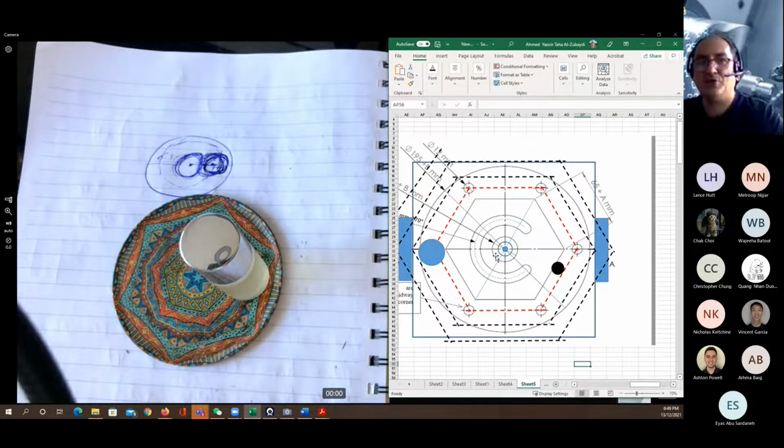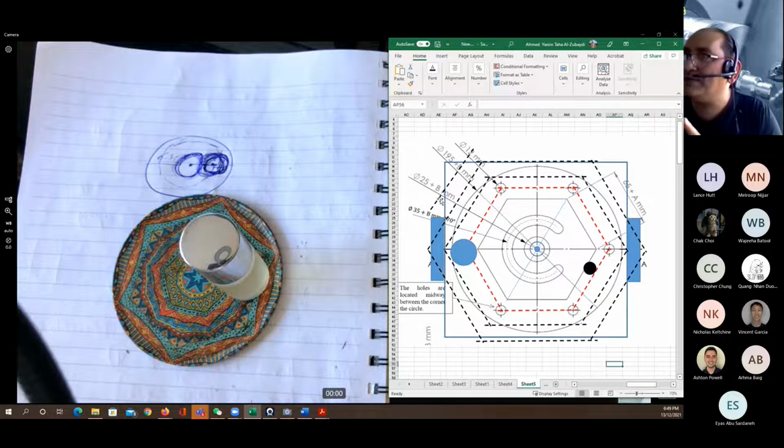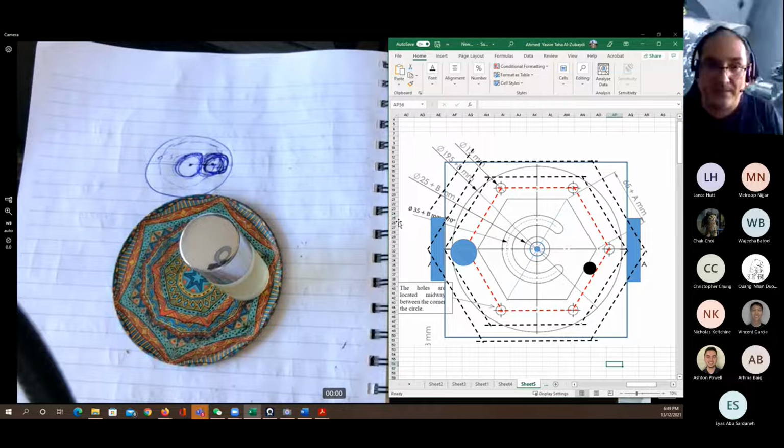Okay, so you subtract when you do the circle interference, circle cut from inside, you subtract. You always subtract. If you're going to confuse with that, use the radius. Don't use the diameter. Use the radius. So the radius of the inner circle, if its diameter is 25 as written here, that means the radius is 12.5.